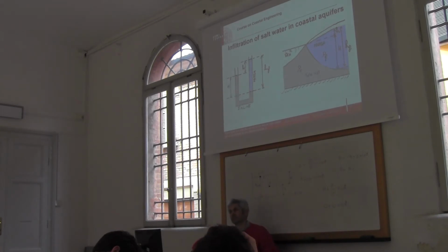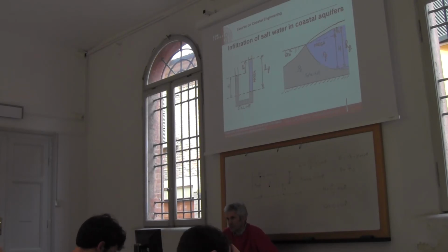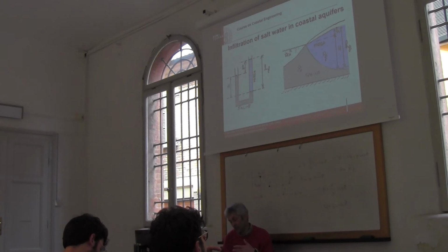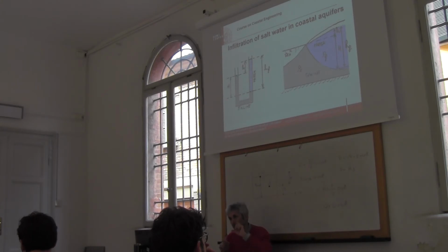And in terms of weight between the saline water and the fresh water? As I said, the fresh water typically has a weight of 1,000 kilograms force per cubic meter. But the saline water is a bit heavier? Yeah, it's 1025. The difference is small, but it's enough to make the difference between the two layers. Yes, of course. It's enough to motivate the fact that you need a higher elevation of fresh water to push it.